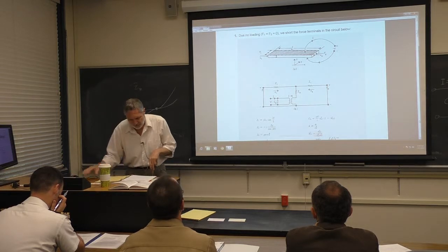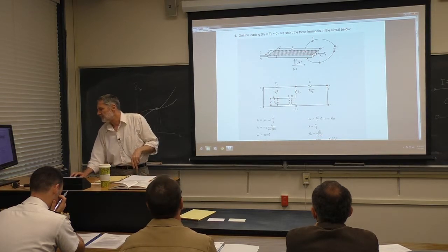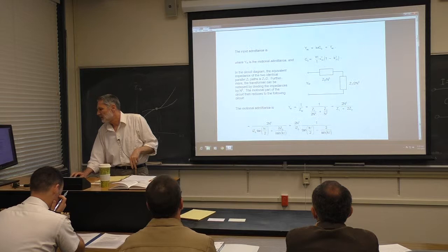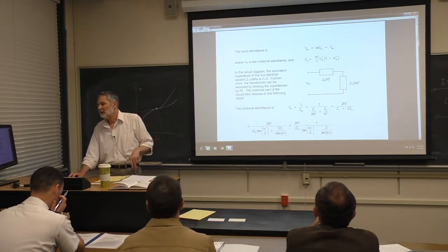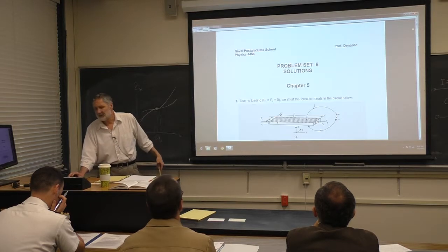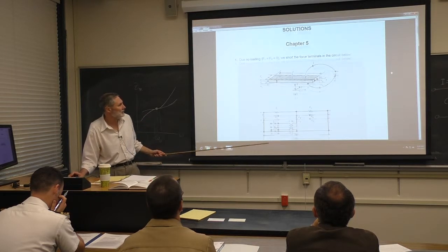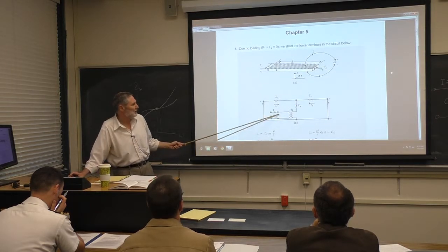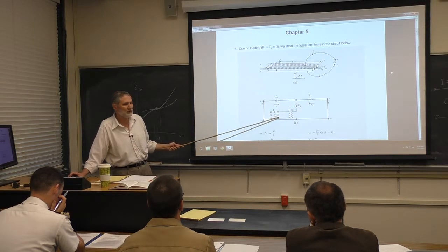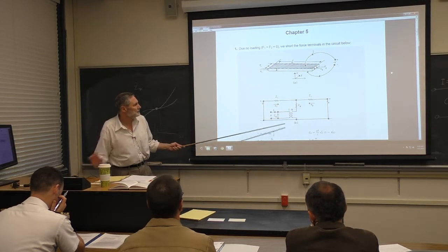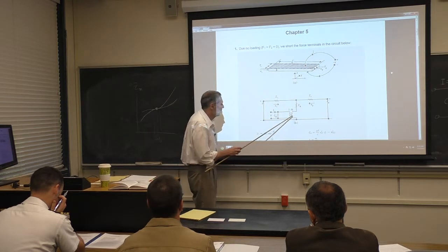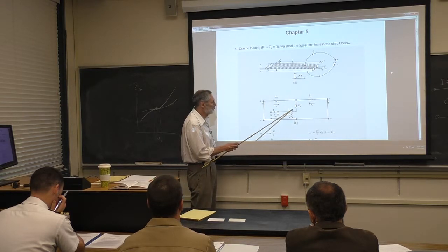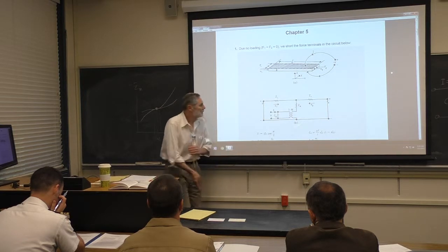Okay, so the admittance is in parallel, so we just add, right? So I'm just going to add this admittance, which is 1 over the impedance, plus the admittance of, you can imagine removing the transformer here in the usual way.